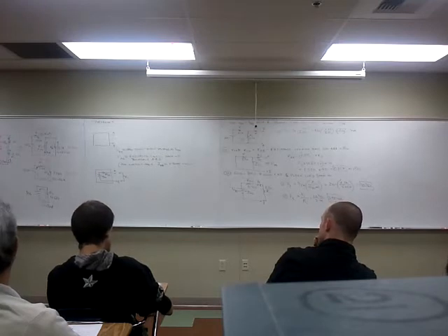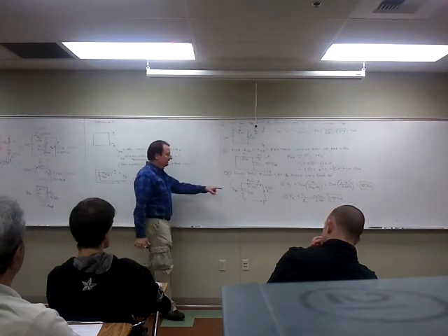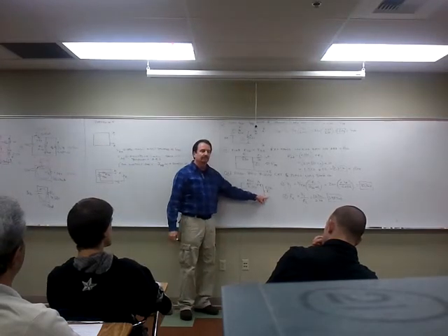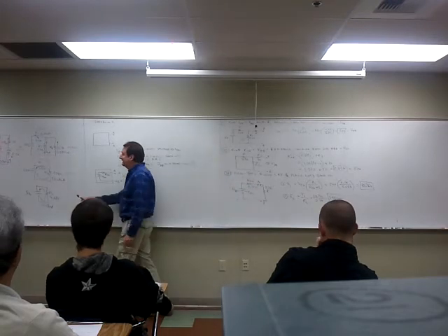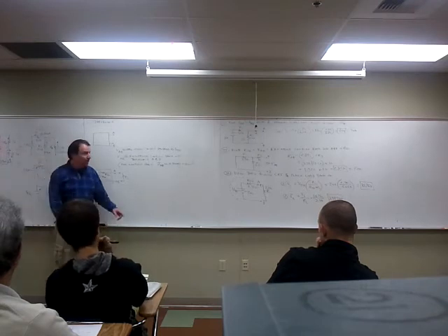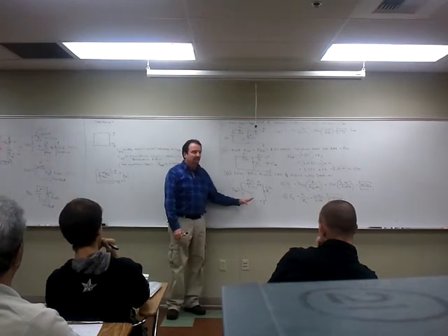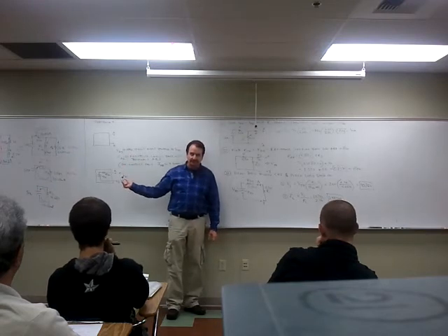Can't you interpolate from that that this dotted line represents a bunch of circuitry? This circuitry is equivalent from the point of view of that load resistor. This circuitry drives that load resistor just like that circuitry drives that load resistor. That circuit is equivalent to this. Or another way of looking at it, this circuit is equivalent to the original circuit in terms of that load.